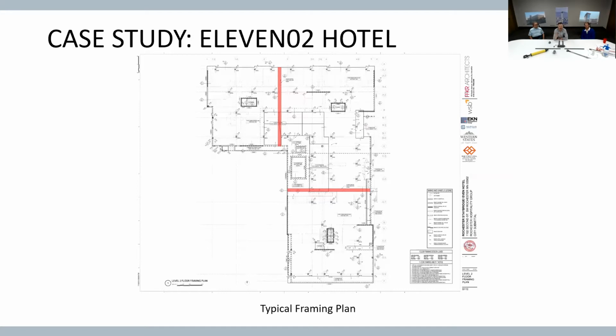Basic layout here, floor plate. As you can see, in red are the pour strips that were originally designed. So we had this layout to work with. And as Jason was talking earlier about stiff elements, if you notice these cores here, there's a core right there, a stiff element. There's a stiff element right there, that dark square. These are cores, stairs, and elevators. Another one right down there. So the concrete wants to shrink to those places, obviously, and that's why we need these strips.